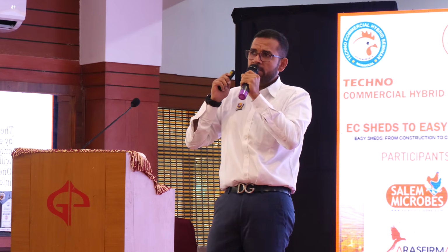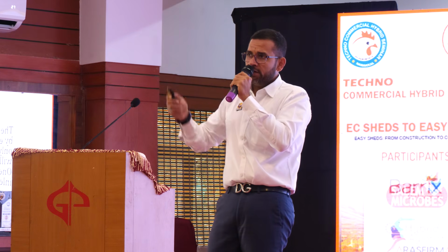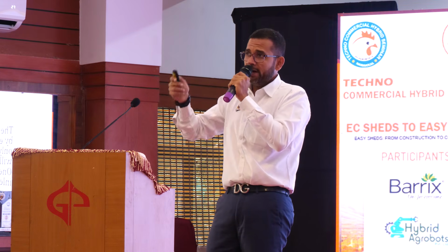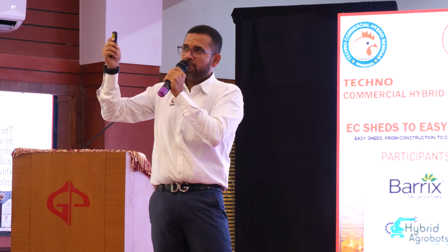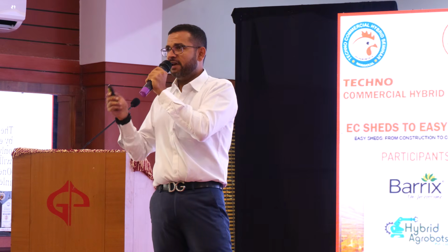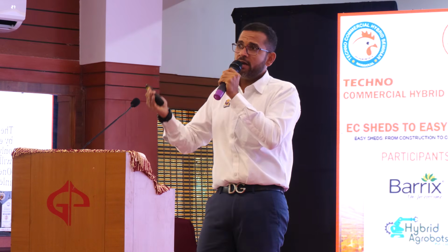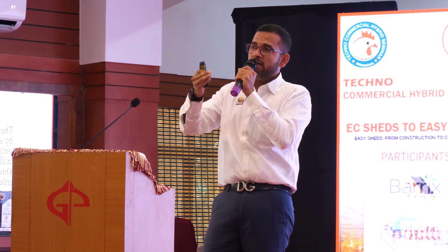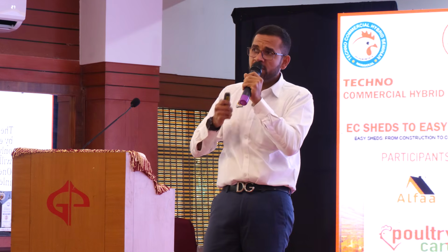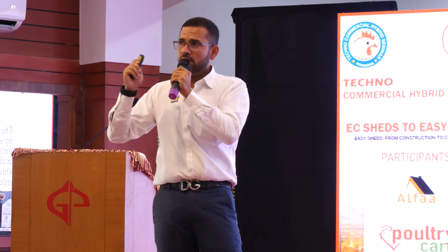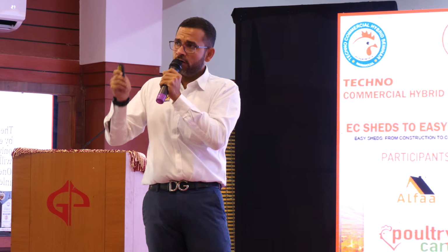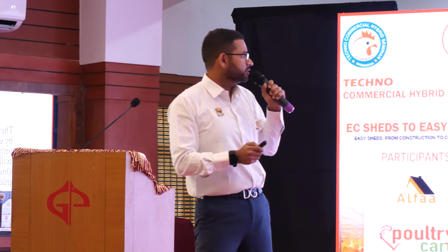So not just cooling pads and fans, but tunnel inlets, air inlets, and correct opening of them, which should also be remotely controlled, is very, very important. The amount of air coming in has to be increased without increasing the air velocity. This is the critical part for correct environmental control systems.